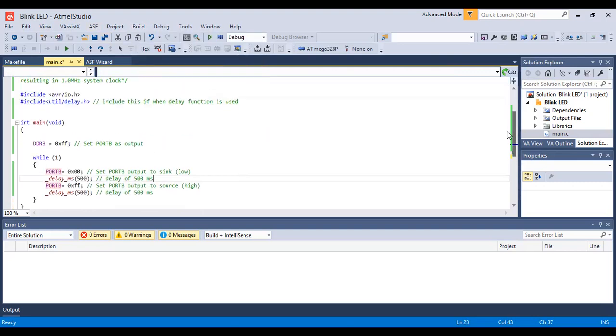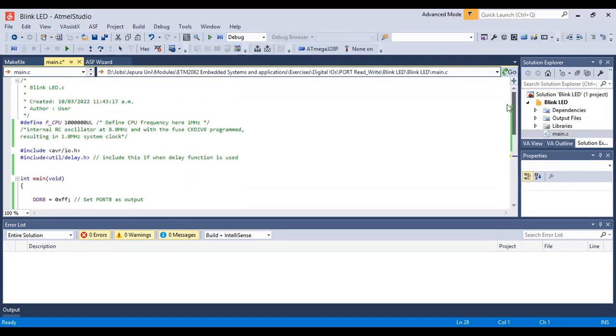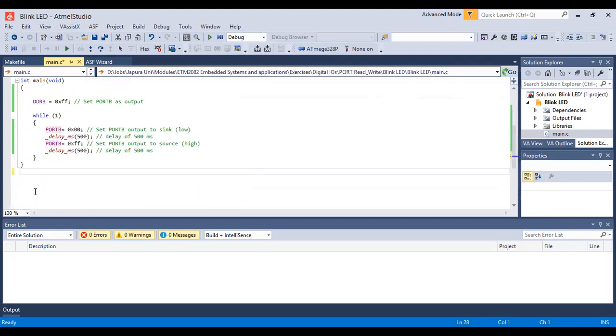So this is a simple getting-started type of lecture for your C code, but I hope the content I have taught is really helpful, because most of the time people make mistakes without knowing what they are doing in hardware. That's why I told you about the use of pull-up resistors, the debouncing effects, the maximum current rating of a pin, and why those protection diodes are there, etc. So you have some idea what you are dealing with. Otherwise, I have seen many students failing and burning the microcontrollers many times because they don't know what they are doing, right?